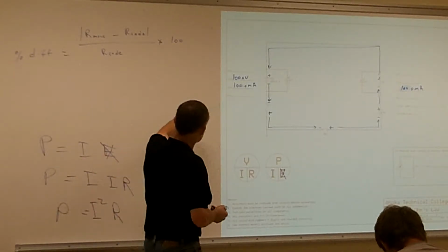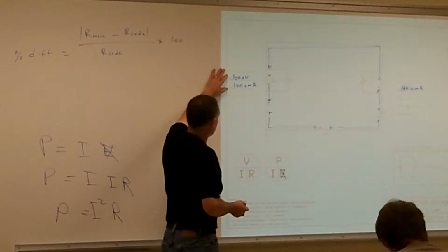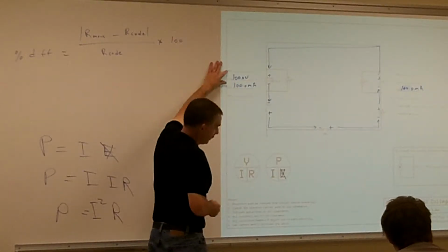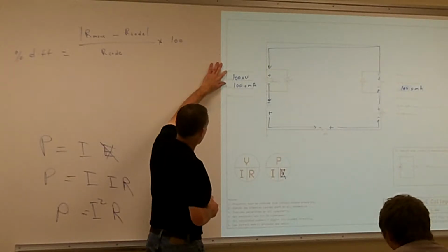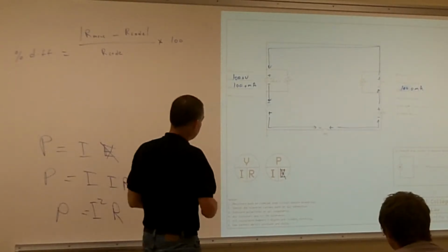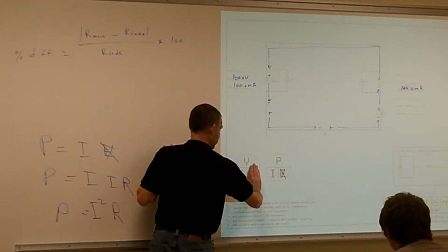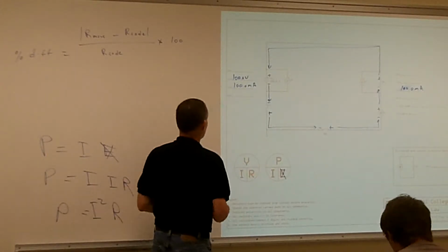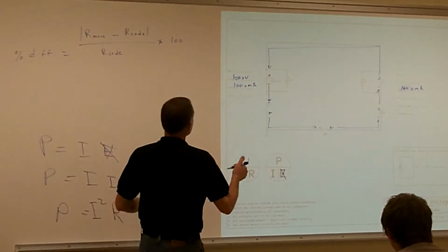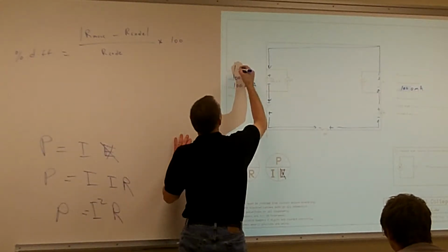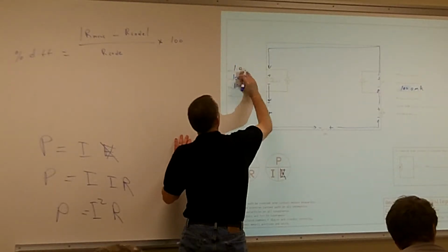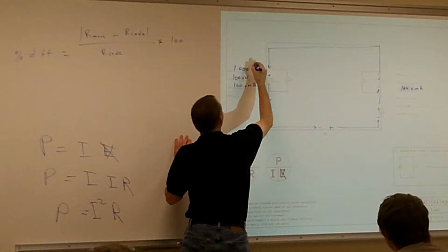So now we know two things, and once you find out two things, then we can find the third and the fourth. To figure out my resistance, how do I calculate it? E divided by I. If I cover up R, I take my voltage divided by my current, and I get my resistance. What's my resistance total? 1 kilo ohm. And make sure we get our four digits.